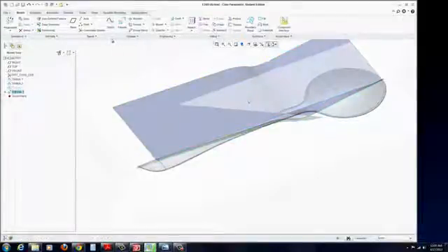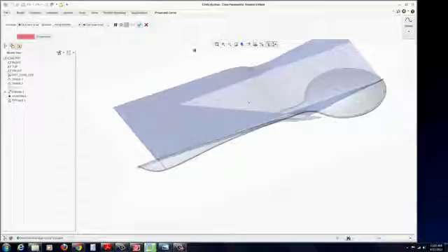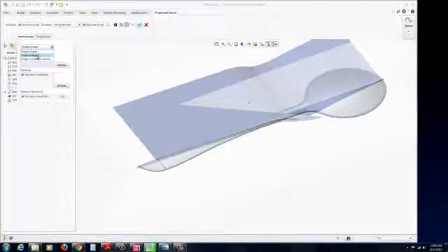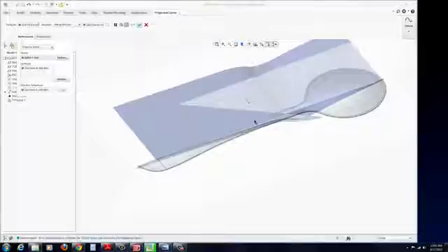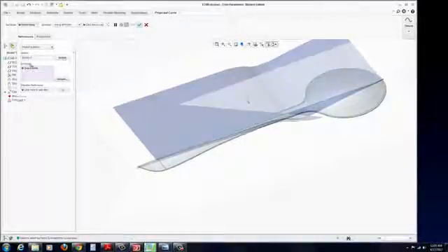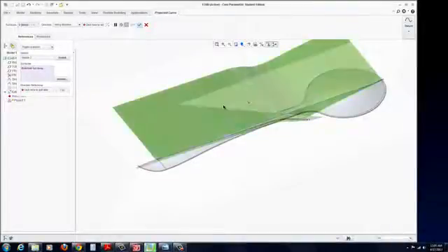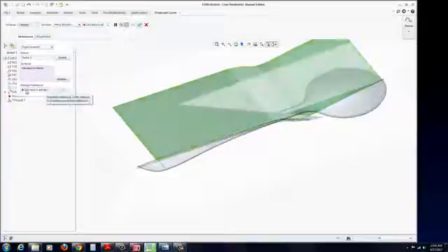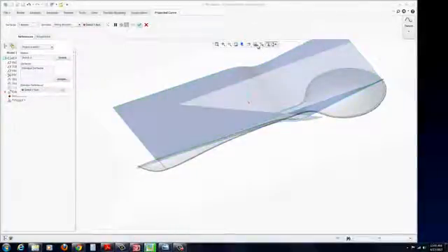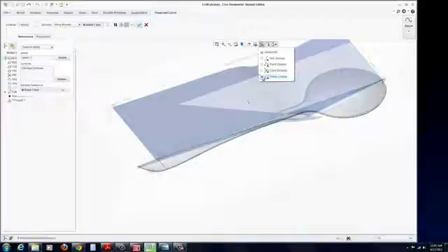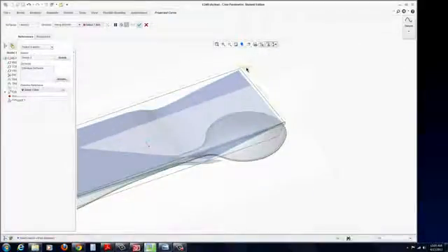Okay, now we could go ahead and use the project tool. And I'm going to reference here. We want to project the sketch. So select that sketch right here. And the surfaces, in this case it's just one surface, so we can just select it. You'd have to hold control if it were multiple surfaces. And then the direction. I'm going to turn on our planes. And once we got that, we can just select the front plane.